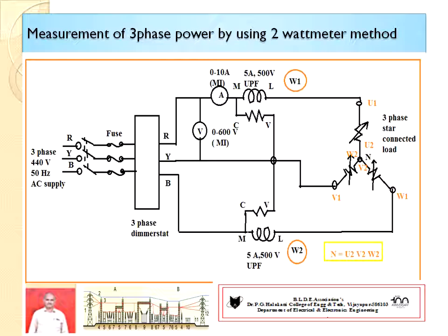In each wattmeter connection we have to give one more external connection from M to C, and C to V, which is internally connected. It represents the potential coil. From the external connection, V to the Y line, both wattmeter voltage coils are given to the Y line common point, because Y does not have any wattmeter. After that you have to connect one voltmeter between the R line and the Y line.